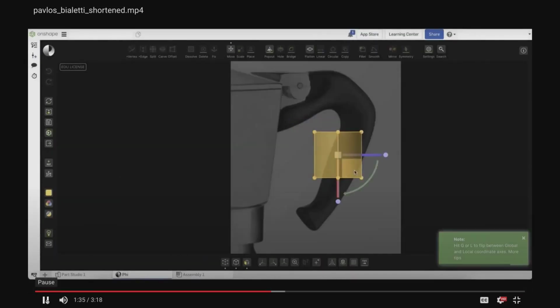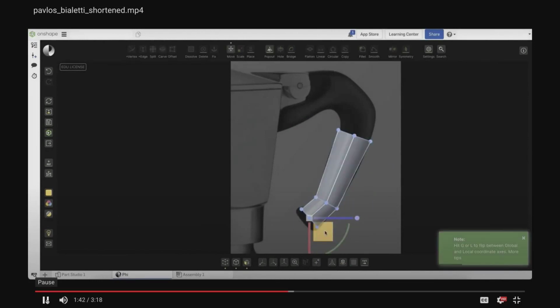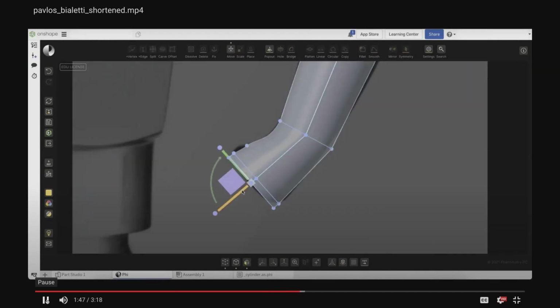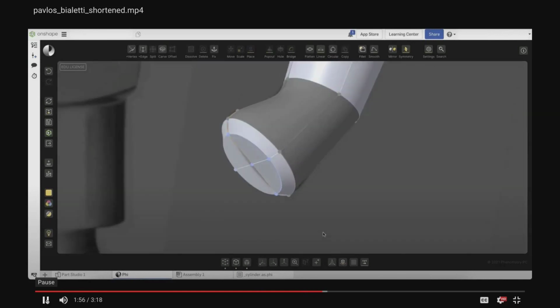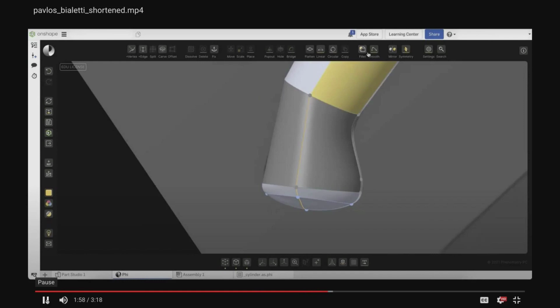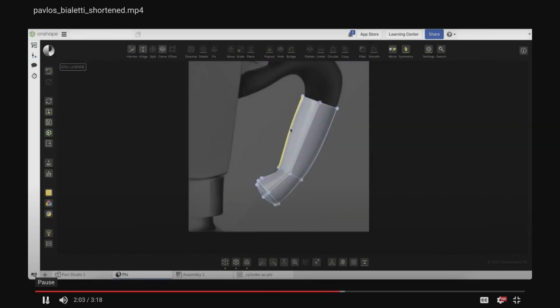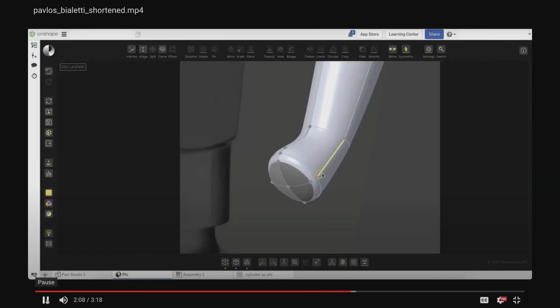So he started with a simple cylinder, which he placed and rotated and scaled. And then with a series of pulls and pushes and pop-outs, as you see, he was able to trace the contour of the handle at the lower part. And then he placed the edges as he wanted and added a smoothness to give it the shape that was required. The gray part that you see is fixed. So what we usually do is we fix parts of our design to make sure we don't ruin anything there as we move on with other parts.